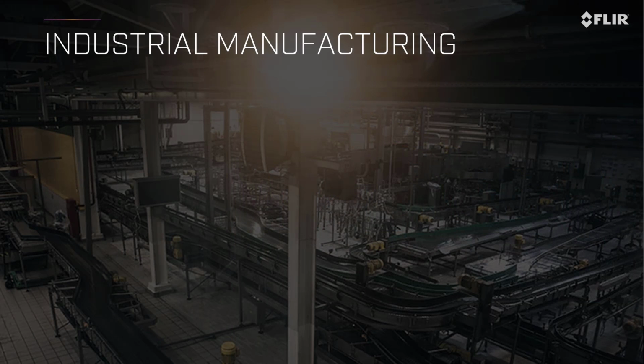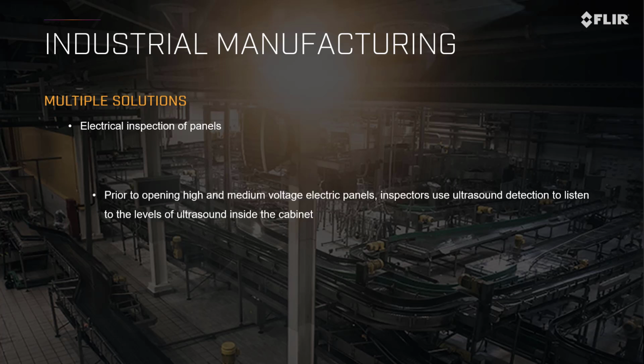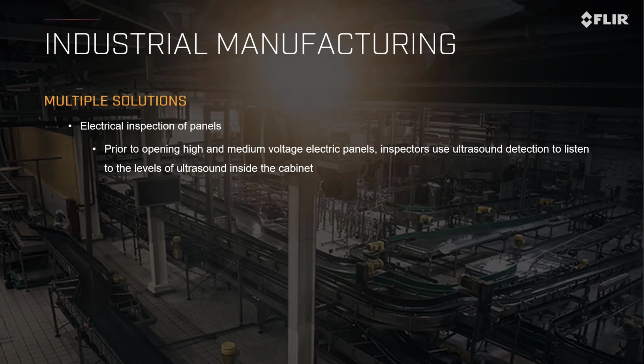But ultrasound technology can also be used in the industrial manufacturing space as well. When we're looking at using ultrasound, there are multiple points of failure you can look at. For example, inspection of electrical panels themselves. When it comes to safety, prior to opening up some of these high voltage panels, we can listen for anything amiss via ultrasound. We want to make sure we keep people safe. In addition to that, we can look at bus ducts. That's another area that we might be able to take our system and point it upwards.